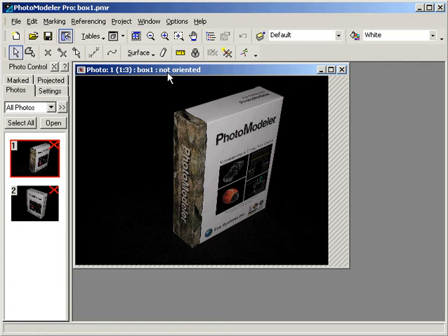Photo Modeler has various tools that help you work with photos efficiently. The zoom tools are very useful, and you will find yourself using them on a regular basis. The main zoom tools are accessible from the toolbar. Here we will demonstrate them. The Zoom In tool is used to magnify the photo. Once the icon is clicked, the cursor changes to reflect that the current mode is Zoom In. We then click over an area on the photo, and Photo Modeler will zoom in on that section.